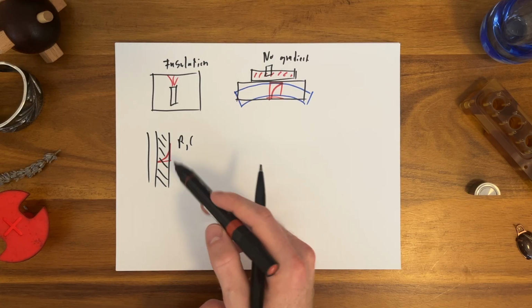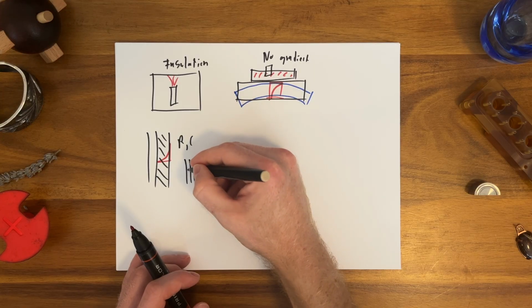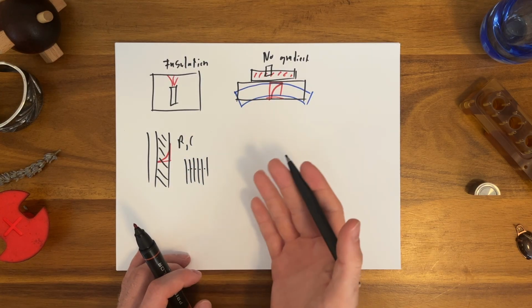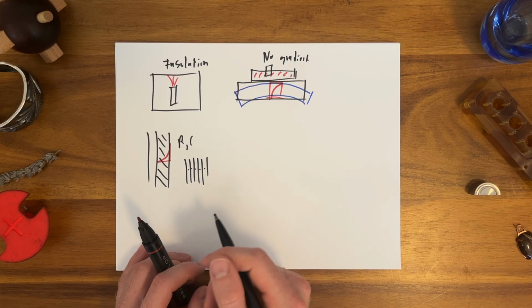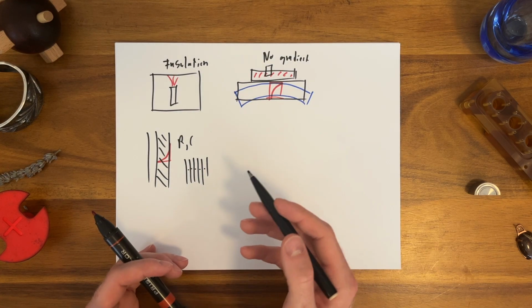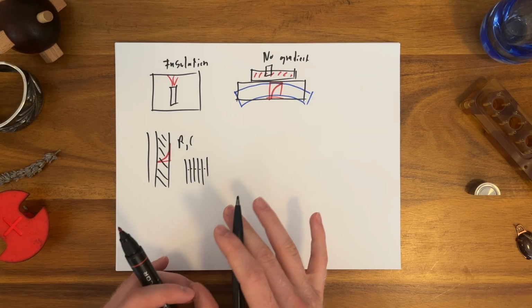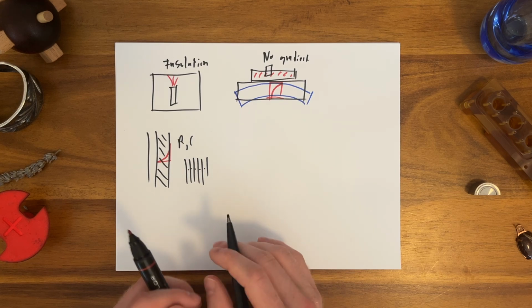So if you wanted to use these kinds of techniques, you've got to chop it up into a ton of R's and C's, a bunch of little regions that are all connected to each other. And you can do that. You can write a nodal network model. You can write a finite difference equation. You can do FEA. It takes a lot longer. You're going to be spooling up this huge program. So the way we can solve these problems easily is with transient thermal diffusion.